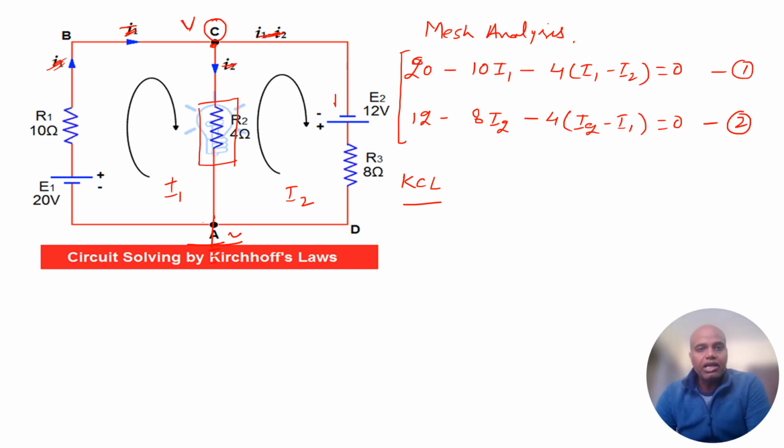So here I'm applying the KCL at this node. You can assume any direction for the currents, but I'm assuming that all the currents are outgoing instead of incoming, and it also becomes easy. Let's understand that all the currents from the node, in all the branches, are outgoing. Why are we taking this? Because the current will be outgoing only when the node C is at a higher potential than the other nodes. So this gives a very simple explanation.